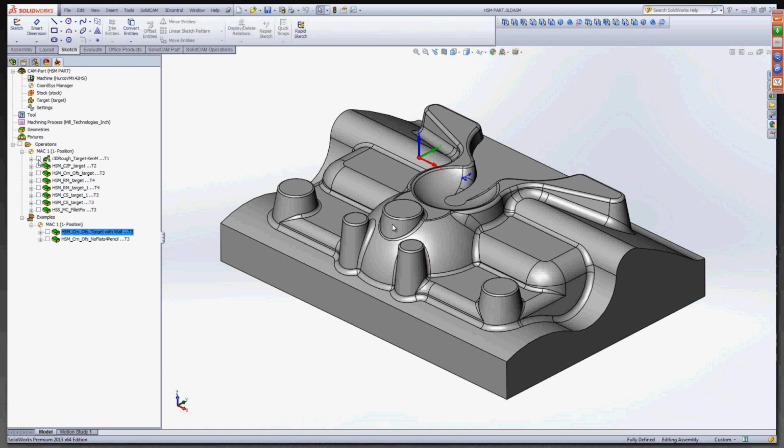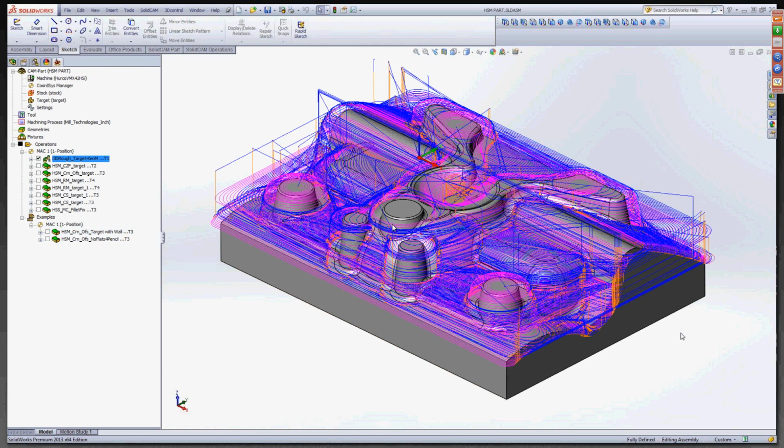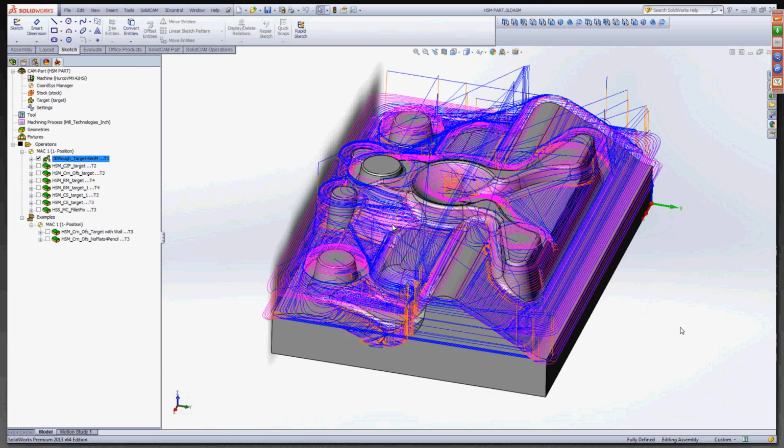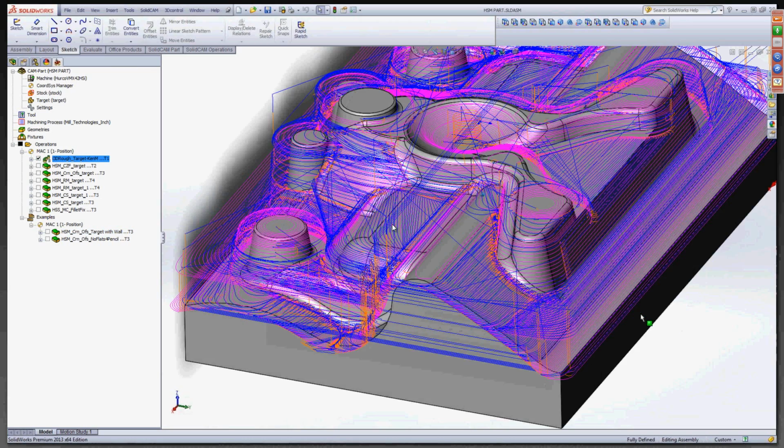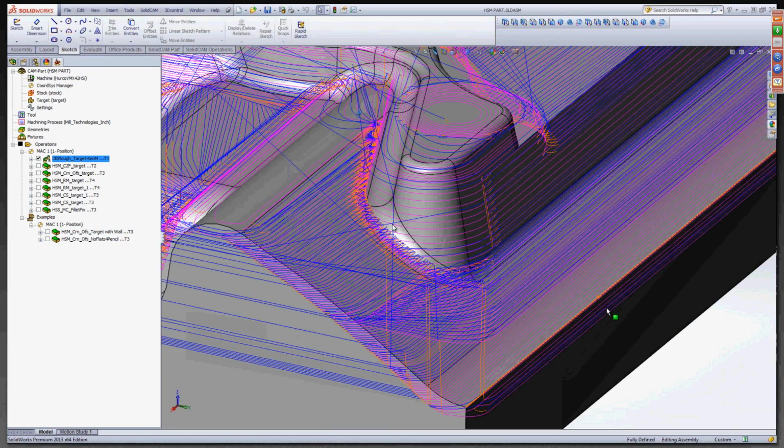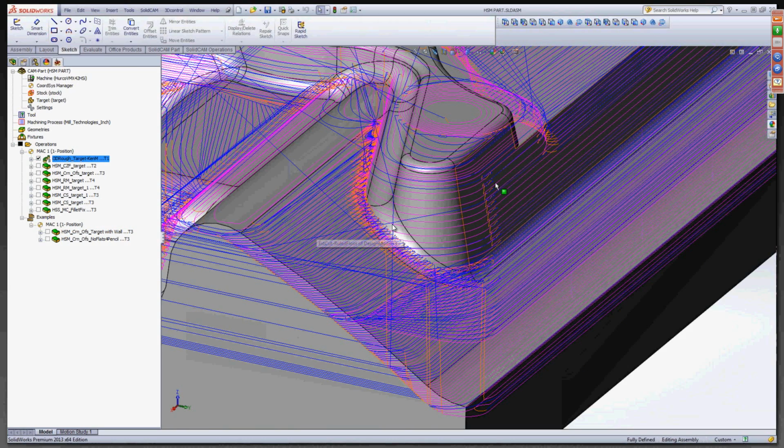There's something really powerful we talked about in the 3D iMachining, the way it does the scallop height. Now, I want you to pay attention to this area right here and this area right here. We have two different angles of walls, and yet the step up is managed automatically by the system such that it creates the same scallop. That looks a little bit weird. When you look at this, you think, well, these have a lot bigger Z-step than these do, so wouldn't those be different? Let me show you what that looks like in reality.